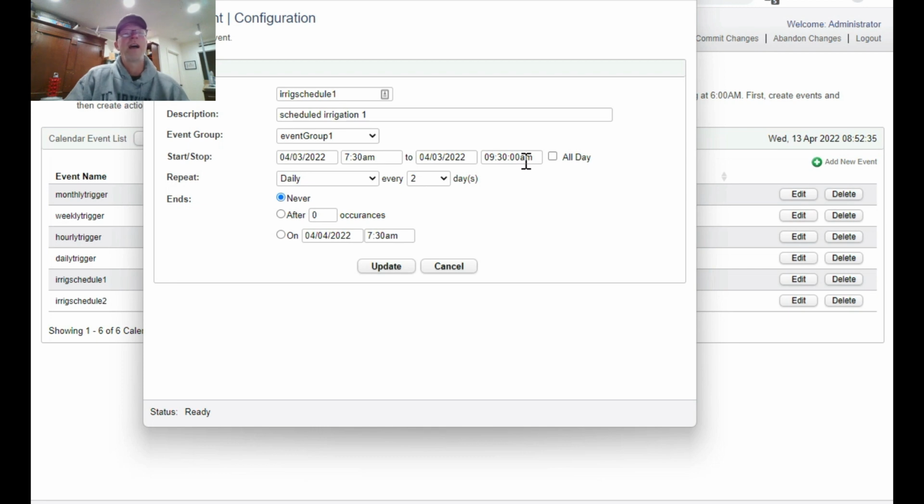So we're using half gallon per hour drip irrigators. So we're basically just putting 1 gallon of water on the vines per vine right now every other day, and it will just monitor that soil moisture and correct it as appropriate.